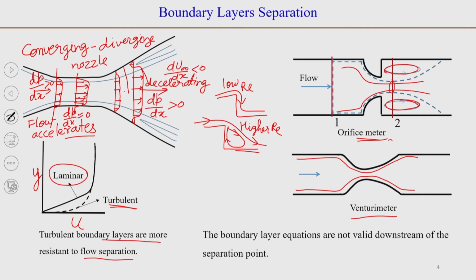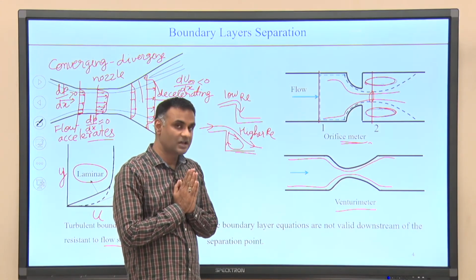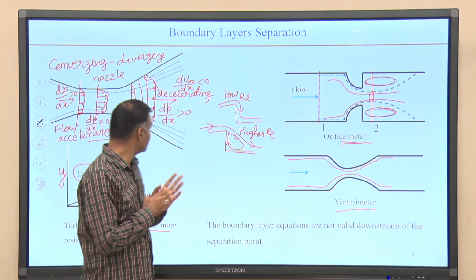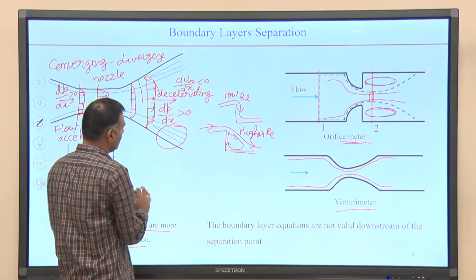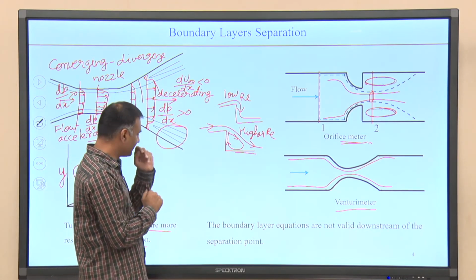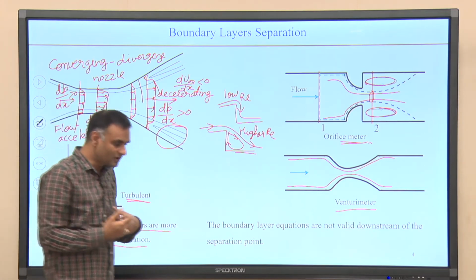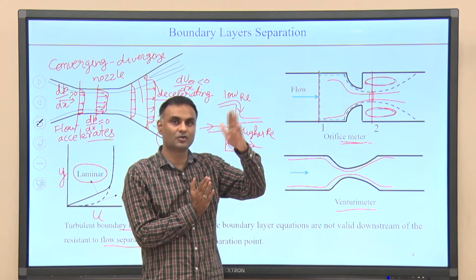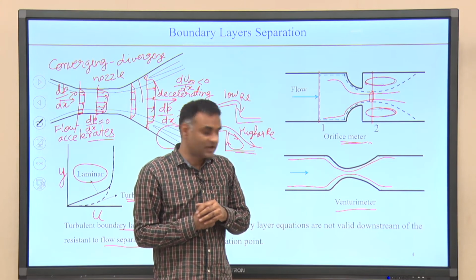Now, when we derived the equations for the boundary layer, we did not have the assumption of separated flow. And when we have separated flow, the streamlines in the outer region also diverge, or go further apart, because the boundary layer becomes thicker.